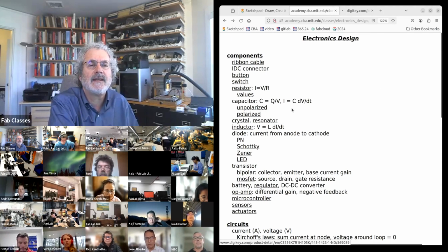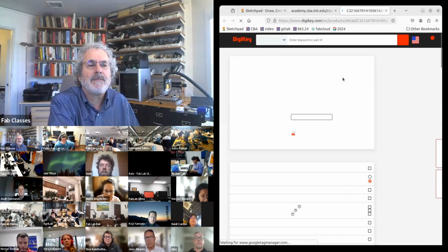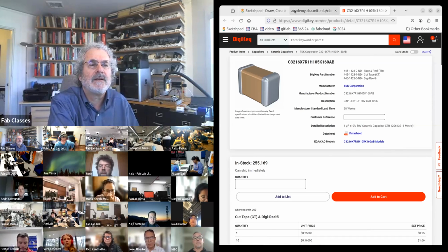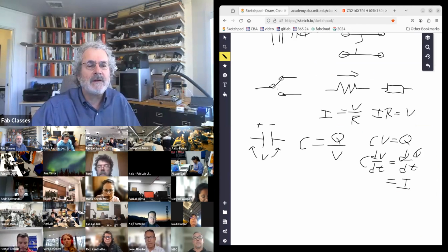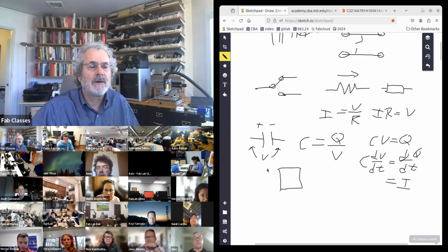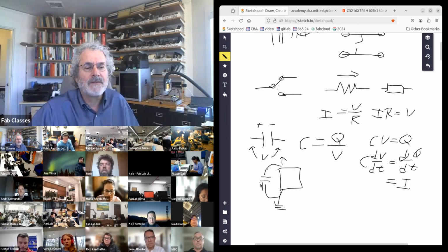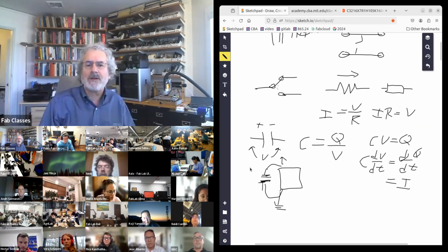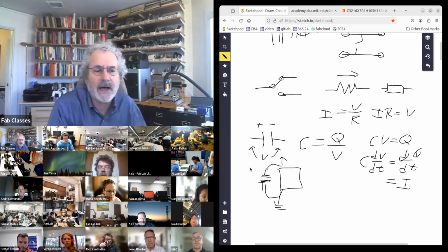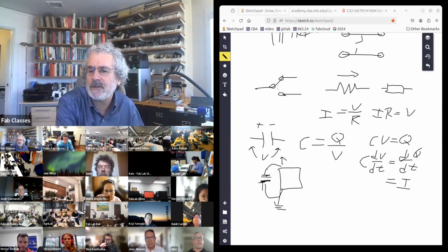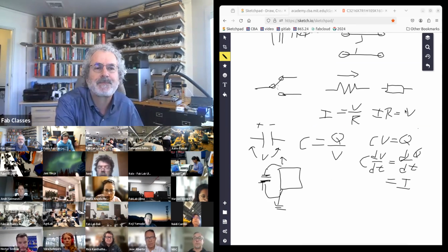And so here's a capacitor. And so commonly, you'll see, for example, when we have a microcontroller, we'll put a capacitor next to it between the power supply and the ground. Or I'll talk about this when we have voltage regulators. And this stores some charge by a component to help supply it when it needs it, and it helps filter noise around it.